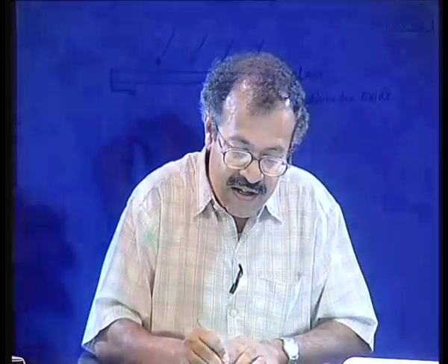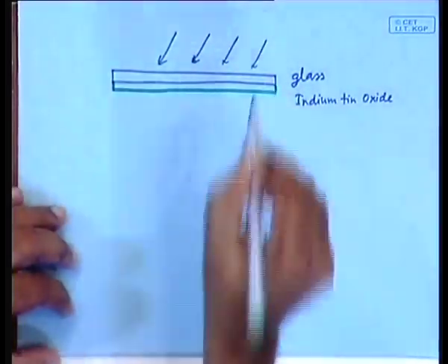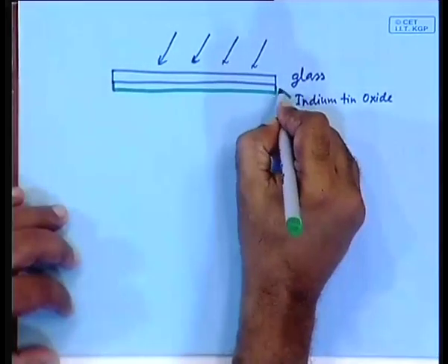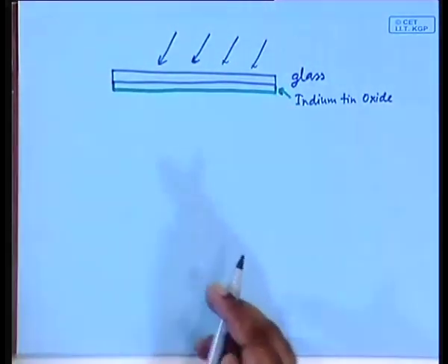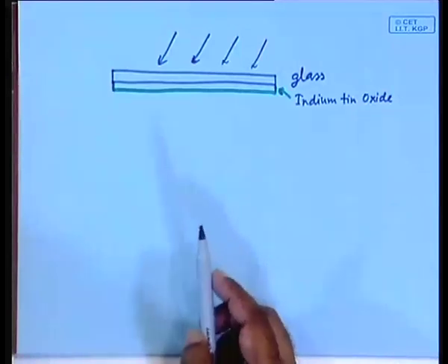Okay. So, a trick is that the indium tin oxide also has the property that it is conducting. As a result, that can also act as a charge collector. So, here you have a layer of indium tin oxide first, as the top charge collecting layer.